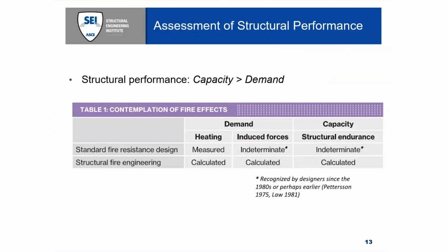To a certain extent, standard fire-resistant design measures the structure's heating using standard furnace testing, but it does not account for the capacity of the structure itself to endure fire exposure, nor does it properly evaluate all aspects of demand, most notably the very important thermally induced forces and their consequence on connections. As an alternative, structural fire engineering explicitly evaluates all aspects of demand and capacity in a similar manner as other design loads are treated in structural engineering practice.